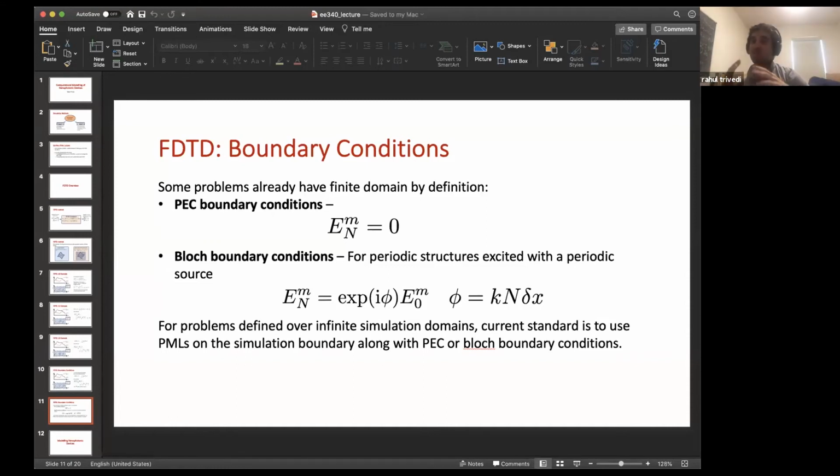And that's one of the reasons why you can put a PML, which exponentially damps your field, and put a PEC boundary condition after that. Once you have an exponential damping, that is much stronger than a polynomial increase in the size of your boundary. So you have a guarantee that if you make your simulation large enough, you're going to get accurate results. How large, of course, depends on what simulation you're exactly doing. Okay, does this make sense? Okay, cool. So we'll take a 5 minute break and then finish the rest of the slides.